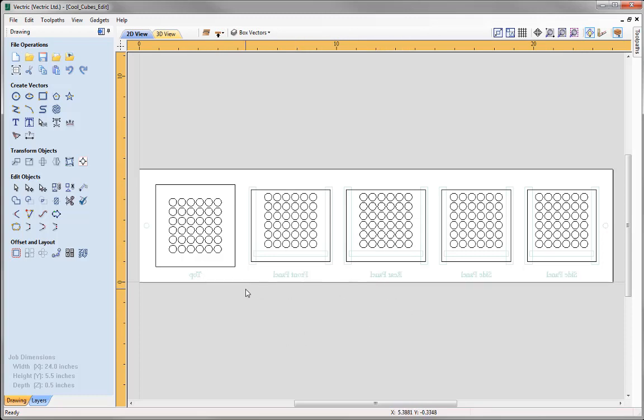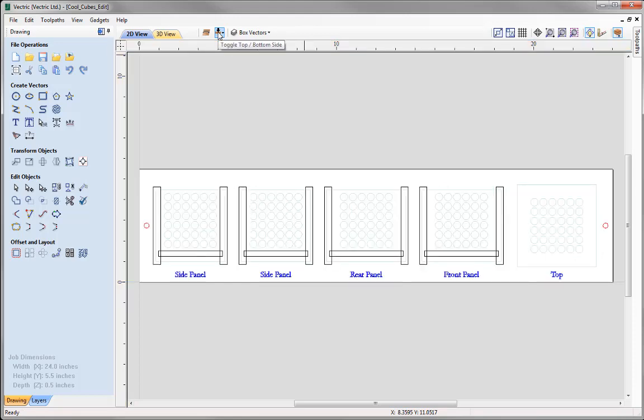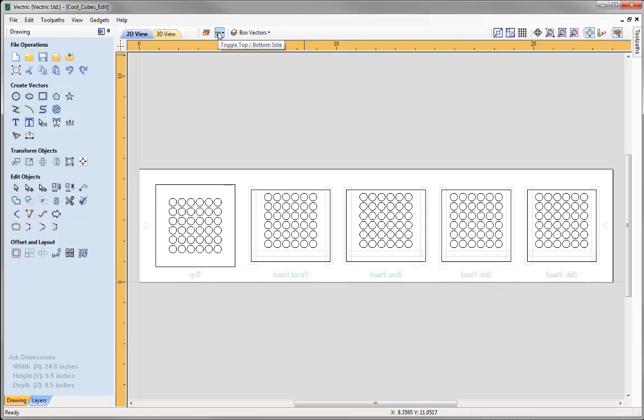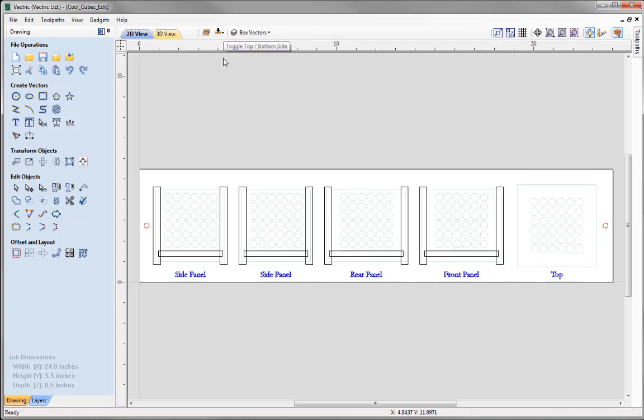Now one thing I want to point out here is that we are using symmetrical dowel holes, so that when I flip between each side, the dowel positions appear not to move, and because they are symmetrical, when we flip the material over, we are guaranteed to have the correct alignment in X and Y, where X0, Y0 is in the lower left for both sides.